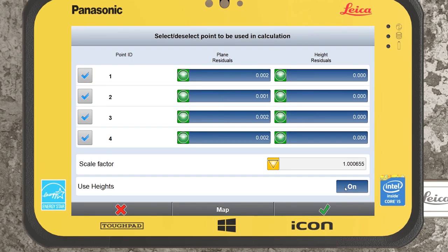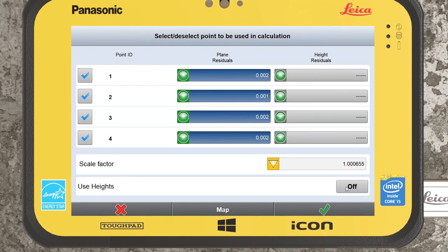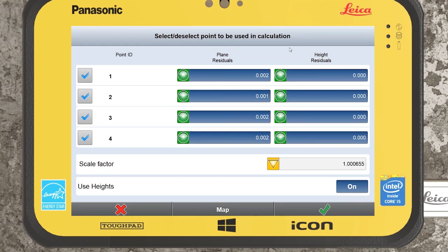We could leave the heights fixed and not include them. However, I would always recommend including them. We are aware that GPS elevations are the most inaccurate part of the GPS observation. So we would always recommend the use of localizations out on site. Even if you are already getting good results, and we're staking out our control points and they're falling in within 20 mil in elevation, you can improve your accuracy and how well they tie in to your local site grid by conducting the localization.